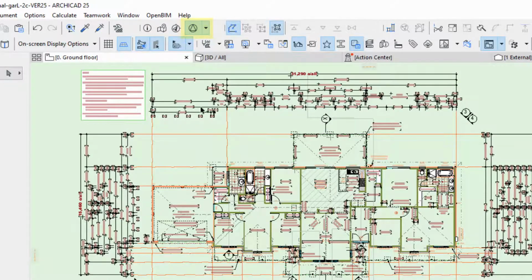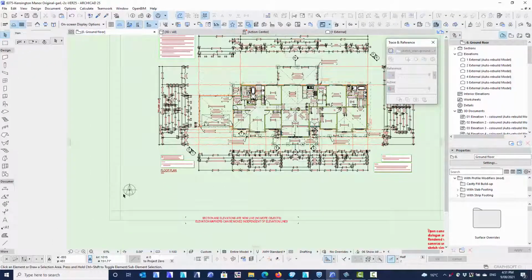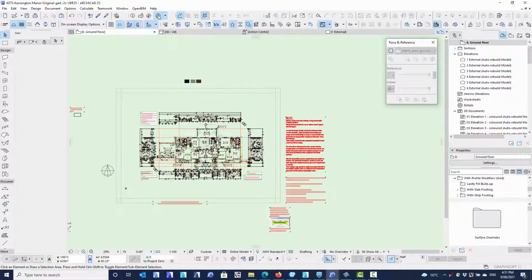Basically, you just click on this and say, look, that's where I want my survey point. It can be moved wherever you like. It can be rotated. It's linked to the north point in the fact that it will show the north direction, but it's actually a position as well. So again, we've got a reference point to a known datum, if you like. But as I say, it's probably not something we need to worry about. That button simply turns it on and off. And there's options here where we can rotate the survey point and show the survey point coordinates.